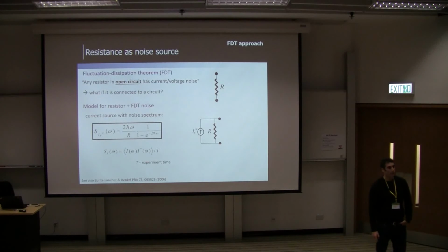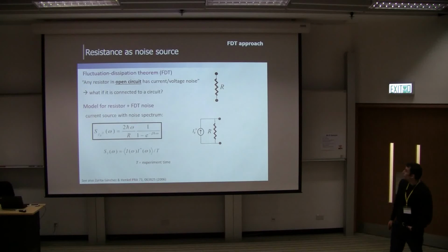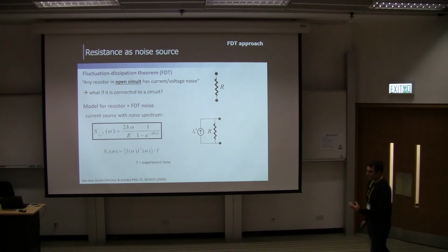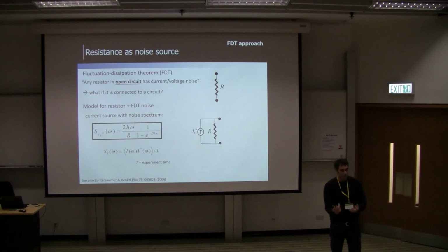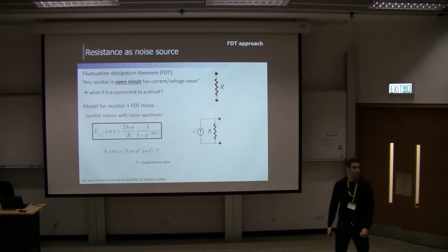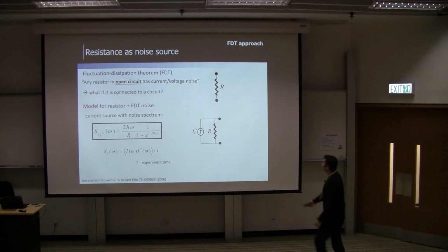You need two impedances, not necessarily resistors. Because if you have just one resistance, from where do you get the noise? Because the resistor has these moving charges in it because of temperature, this is the noise current, the voltage you have. It has to talk to another part of the circuit, right?